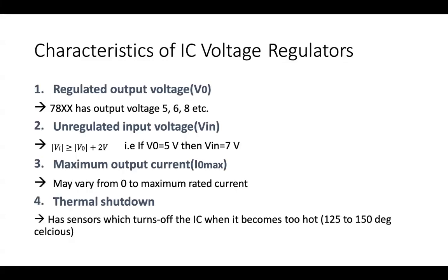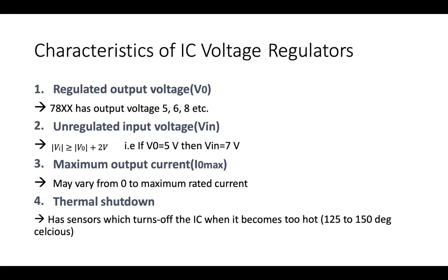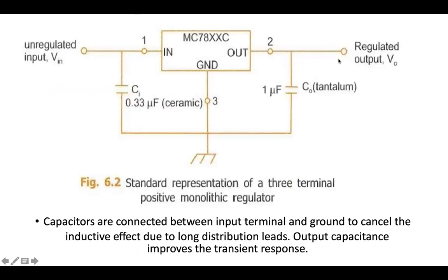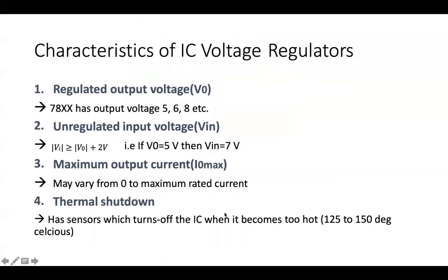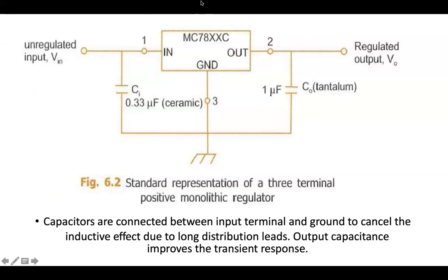So we have certain advantages. The best one that I was mentioning to you about is the thermal shutdown. But after the circuit, the circuit protection can be enabled, which means after the circuit here, we can probably include a small circuit which can actually have a fuse built in. So that's the only way we can make changes to this MC78XXC series.